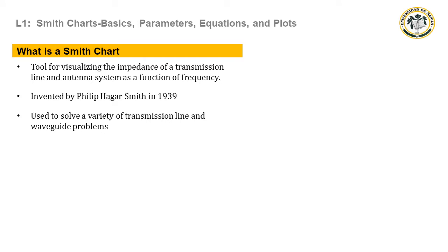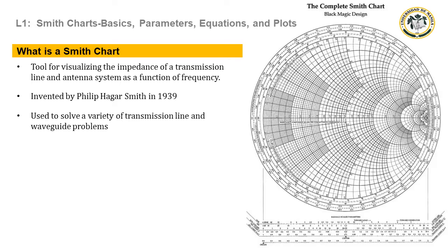So Smith chart is really just a plot of complex reflection coefficients overlaid with a normalized characteristic impedance that's 1 ohm or the admittance of 1 mho. Although calculators and computers can now easily give answers to the problems, the Smith chart was designed to solve these problems remains a valuable tool. So this is an example or an illustration of the Smith chart.